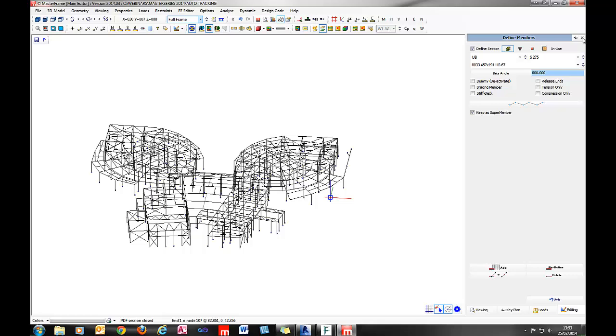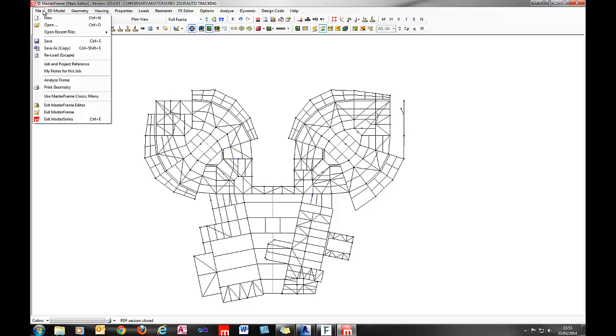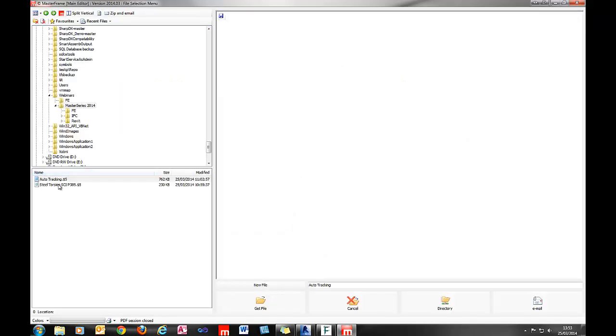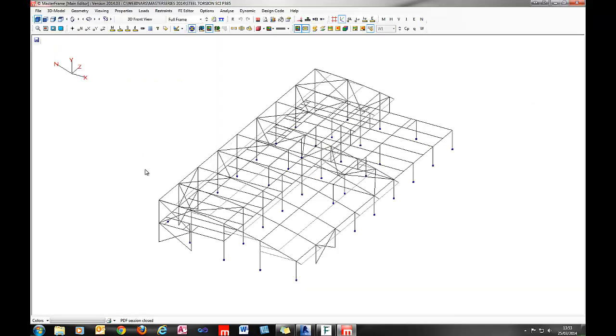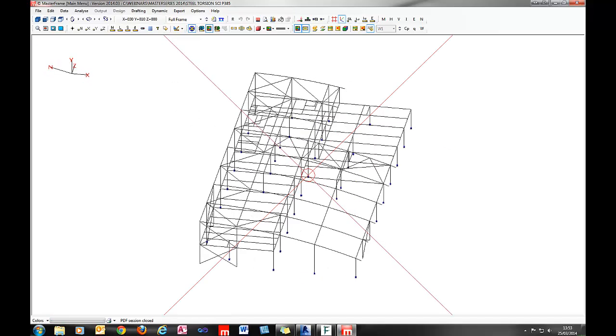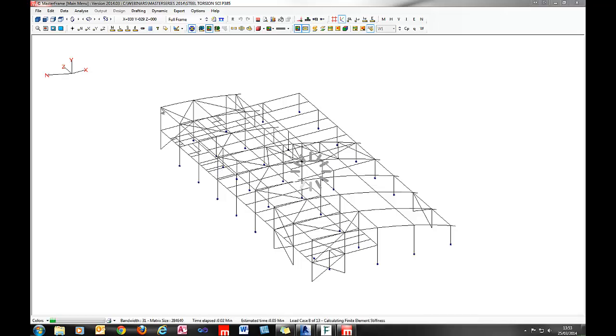Now, I also wanted to review one more new feature which is reasonably significant for 2014, and that's the introduction of the SCI P385. We've always had the ability to go with SCI P57, which obviously is applicable to the British code, but for Eurocode there wasn't any compatibility between the P57 and Eurocode. Along came SCI P385 and filled that void.